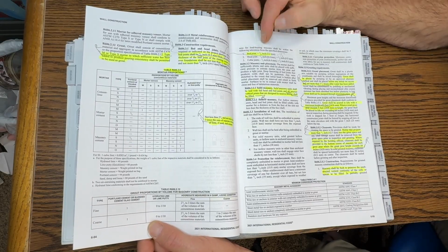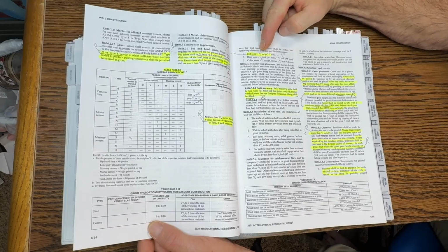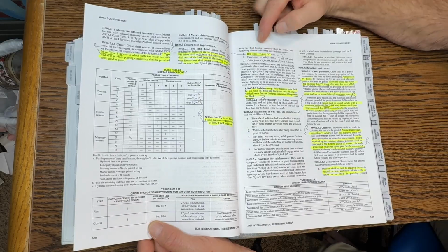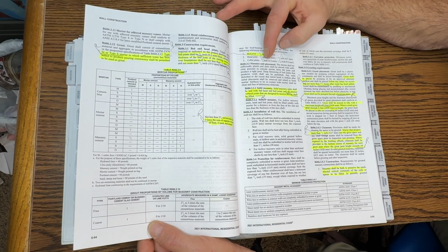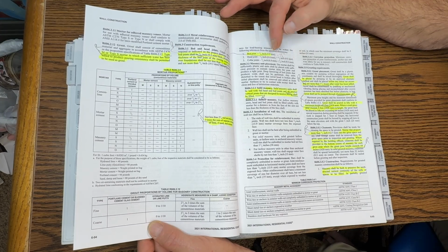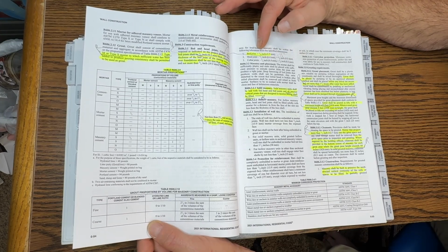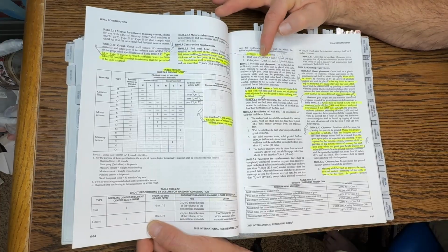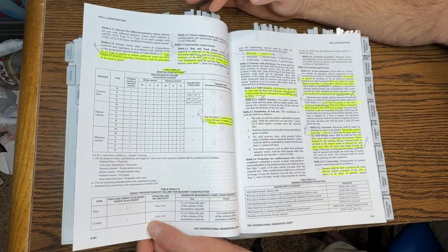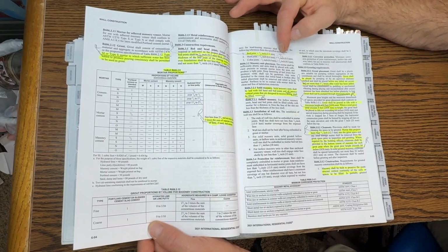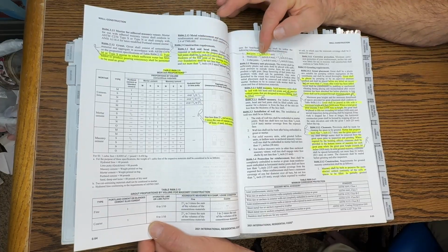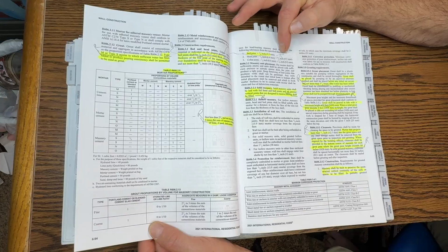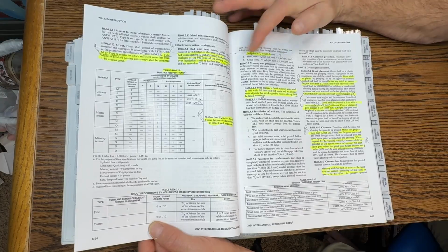Look at this. This is your tolerance. You have a bed joint tolerance of +1/8, a head joint of -1/4, and collar joints of -1/4. So if you're looking for a maximum or a minimum, you have to apply the tolerance. These are more nominal here in 606.3.1. So what that tells me is, for a bed joint, if I start out at 3/8 and I add 1/8, the maximum is 1/2 inch. That's what this is telling me.